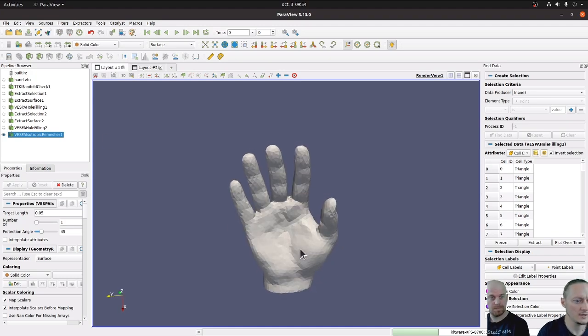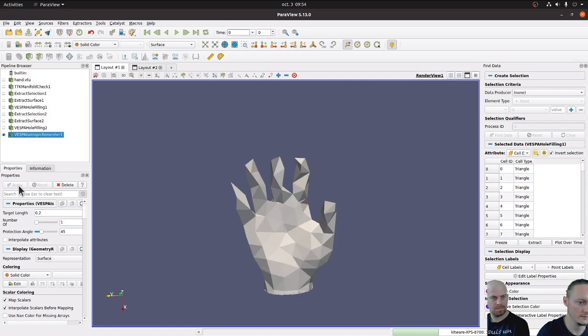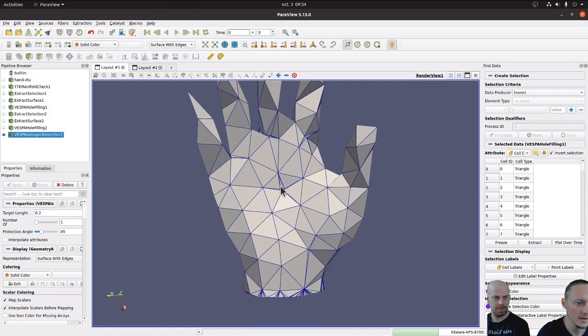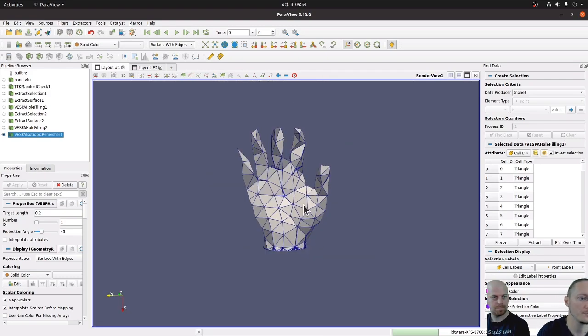What is interesting here is that, I don't know if you have seen, guys, but there is a little part here that stayed from the original mesh, even if I have a too large version. Can you zoom on it, because it's not super clear? I think with the edges it's clear. Yes, here we have seen that there are some initial edges which are kept from the original mesh. In the case of this dataset, there is no real interest to do so. But in CAD meshes, for example, you often have sharp edges that you would like to get in your output, because those are important parts that you do not want to refine.